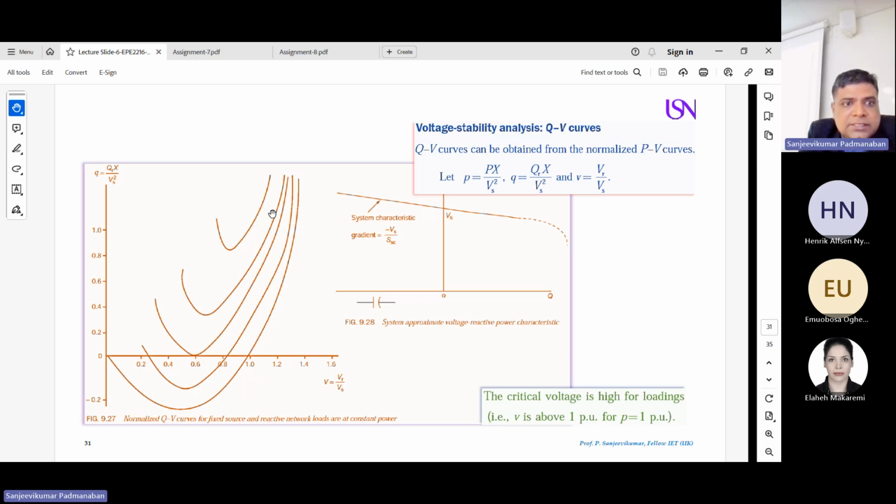And this characteristic decides how you are able to maintain or normalize your reactive power. So we are not interested in these areas. The minimum requirement is 0.6. Then we are looking at the characteristics of reactive power Q versus sending end voltage Vs. You can have a characteristic where Q varies from 0 to plus Q, and 0 to minus Q. As Q increases on the positive cycle,